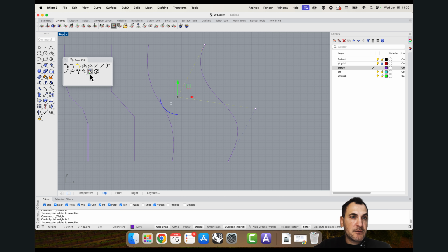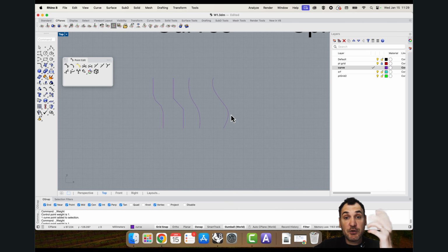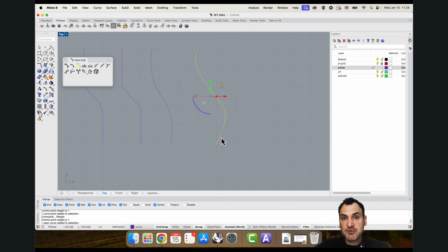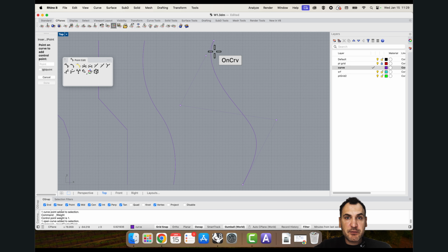So we can also work with these sorts of manipulations to adjust the curvature so that this maintains some sort of fluidity, but we can control this shape. One other thing we can do is add control points or insert control point. And this can work with a bunch of stuff. So you can see here when I do it on a NURBS curve, it parametrically calculates how this information can be traversed on the curve, right? So I'm going from these control vertices along the dashed lines, but I'm choosing a point on the curve.